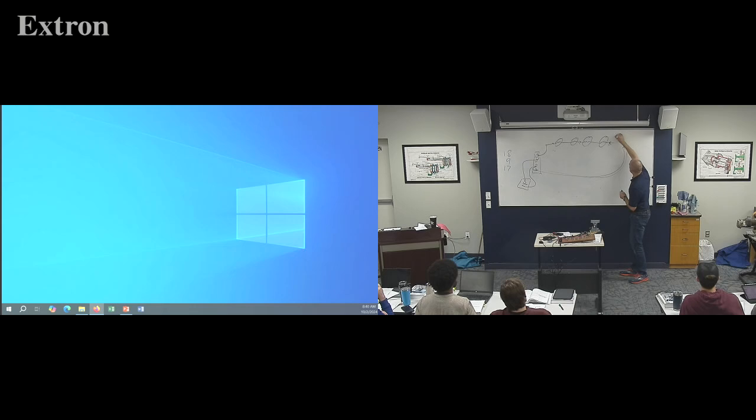Next question, if I were to put an amp meter here, well, now because the wires complete the circuit, we're back to a complete circuit. Even if this is broken, my little amp guys can run through my amp meter and finish the course. So an amp meter allows the amps to go through. A voltmeter is not considered connecting the circuit. It's just taking a measurement. So if this is broken and I put a voltmeter across, it's still broken.